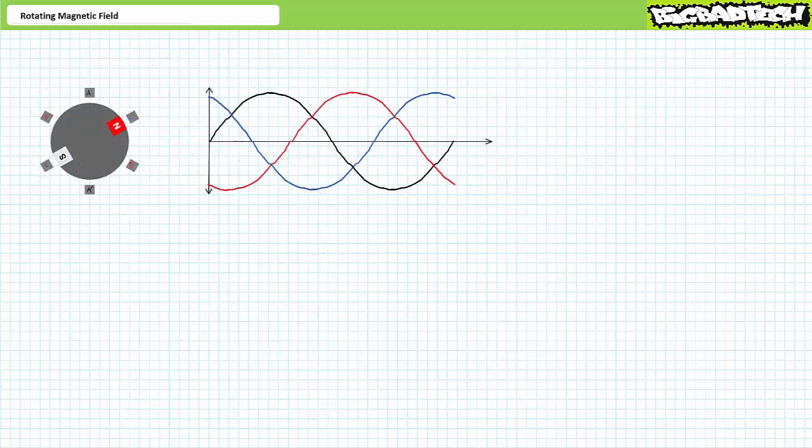Moving on. Now that we've got a general idea of how the properties frequency and the number of pole pairs per phase influence synchronous speed, let's examine an iterative step-by-step illustration of the rotating magnetic field produced in a 3-phase AC stator. Operationally, one might think of a pole pair as an angular stopping point on the way around a full 360-degree circle. Allow me to demonstrate.